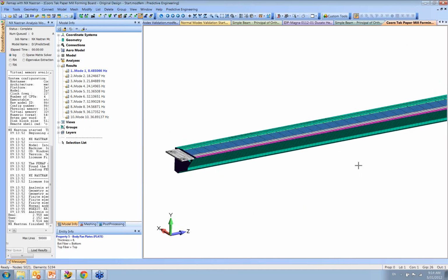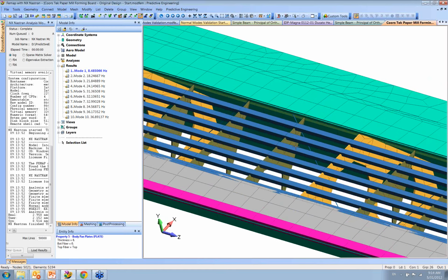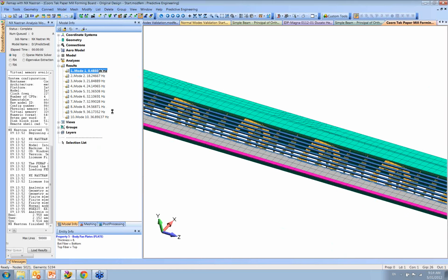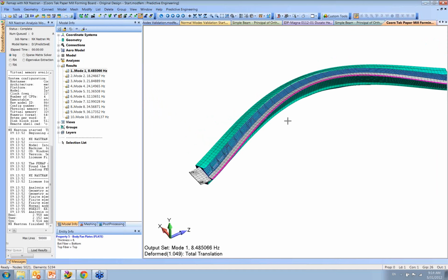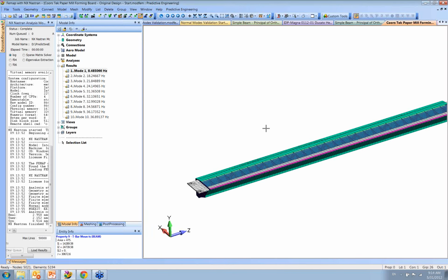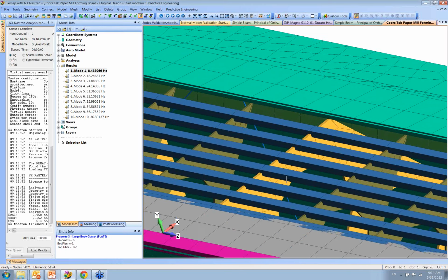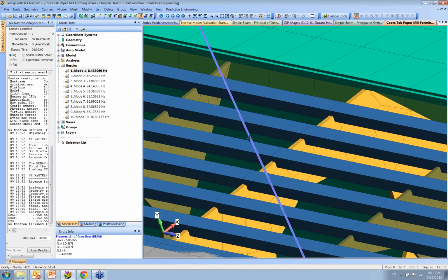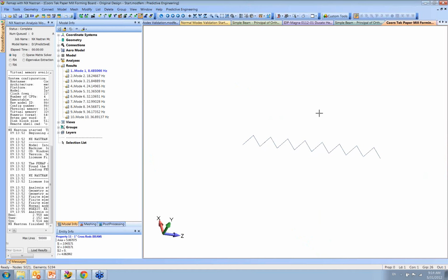Good. So this went on probably about a week, and we weren't getting anywhere until we thought about the mode shape, and we really just started thinking, well, look, it's a beam, it's going up. What we need to do is reinforce that beam. And it was just sort of blind. I don't know. I mean, it just kept looking and looking and said, why don't we reinforce the top and bottom, you know, with some thicker ribs? So we put in this structure right here, and let me show like there. So we put that inside the column to reinforce it, these rods.